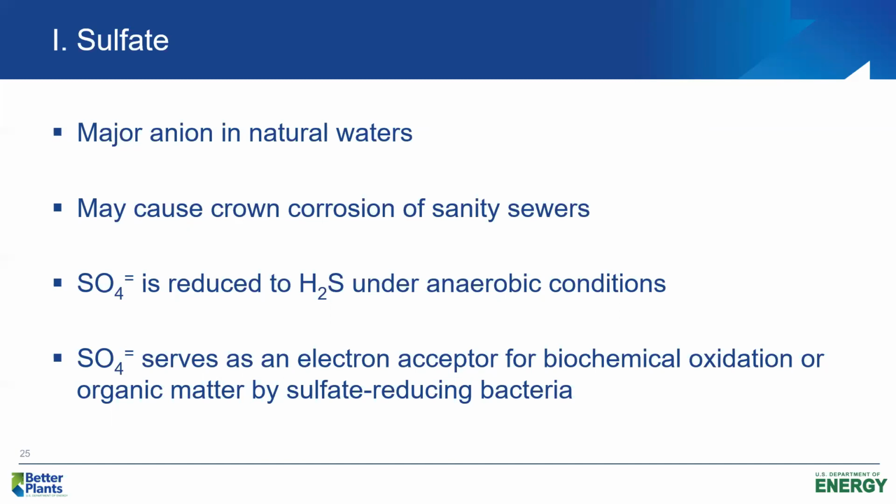And then at the treatment plant, usually at the headworks, as raw sewage comes in, we may have excess levels of hydrogen sulfide that are extremely corrosive to our raw wastewater pumps, and may be corrosive to our screens and even the equipment in our grit chambers. So sulfate, again, under anaerobic conditions, can get converted to hydrogen sulfide.